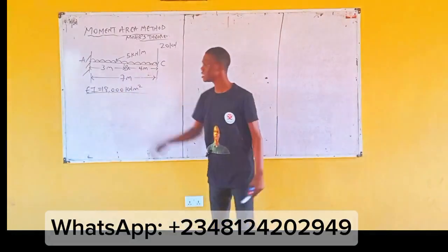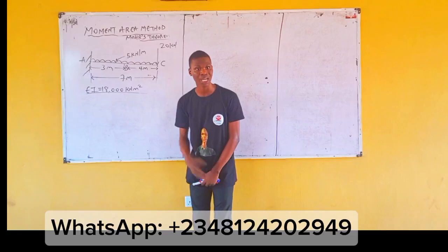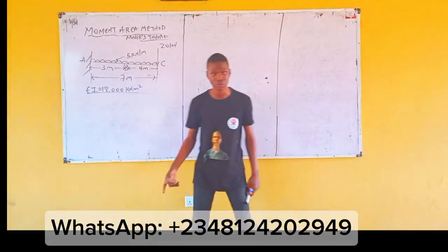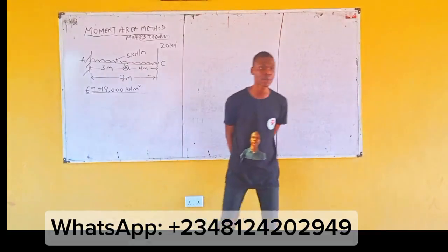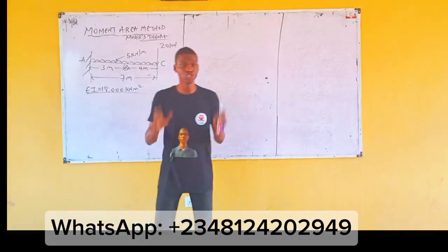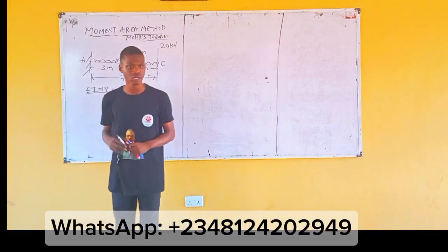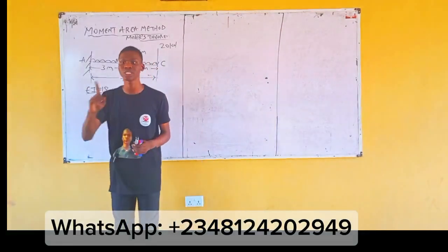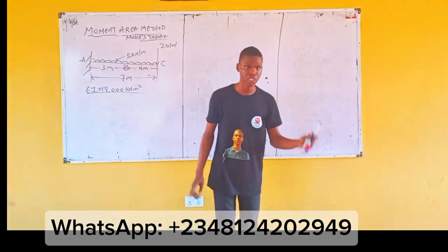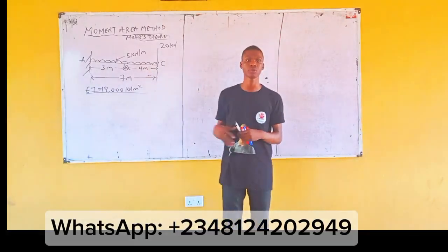Now, this cantilever beam, unlike the previous one which was just loaded with a point load at the free end, is loaded with a UDL and a point load. You consider your UDL separately and your point load separately. Meaning, you draw your beam considering UDL, and draw your beam considering point load. You get the slope due to UDL, and the slope due to point load. Then you add them up to get the slope at whatever point you are calculating.